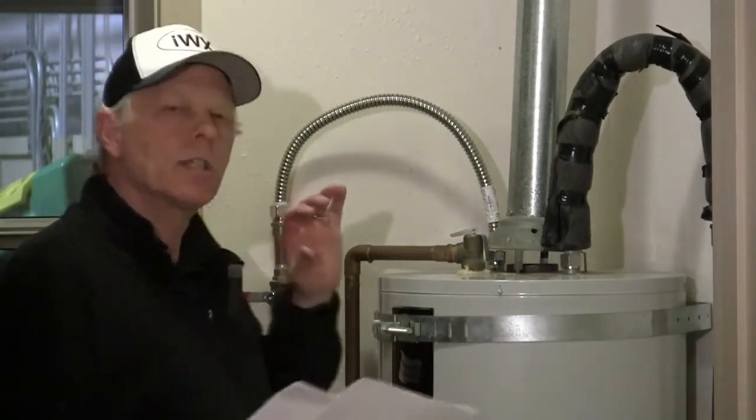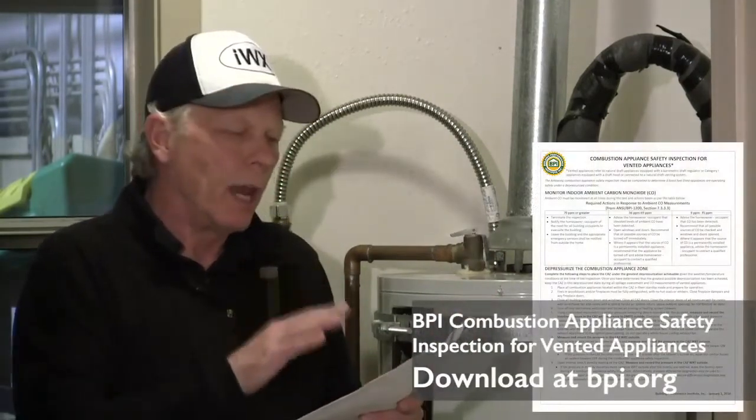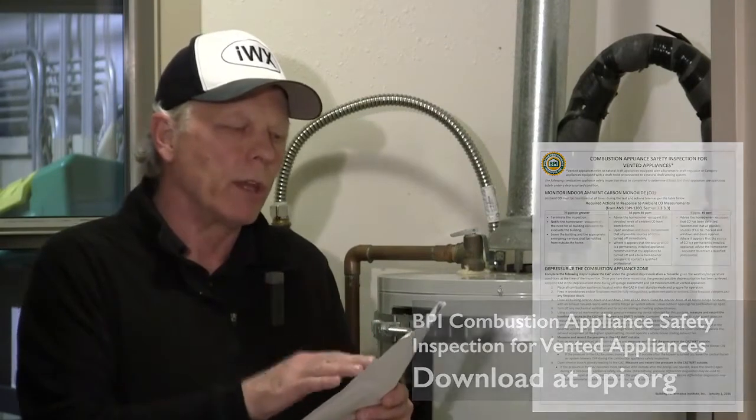Okay, we're going to wrap up our combustion appliance zone testing with line 10. This is where the candidate makes appropriate recommendations for the CAZ according to the current version of ANSI BPI 1200. And that's the recommendations you would make if this spilled. You use the BPI sheet that we talked about earlier, and on table D1A on that sheet are test results and then the actions that go along with it. The title of table D1A is Action Levels for Spillage in Combustion Appliances.